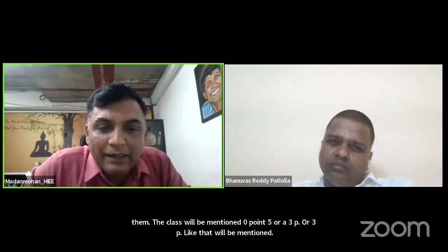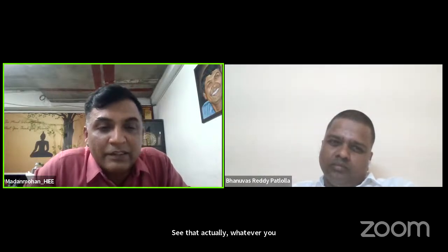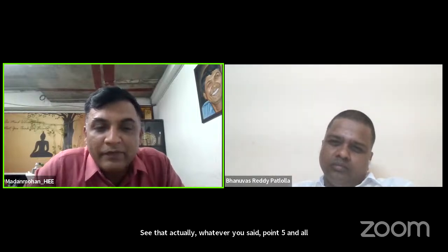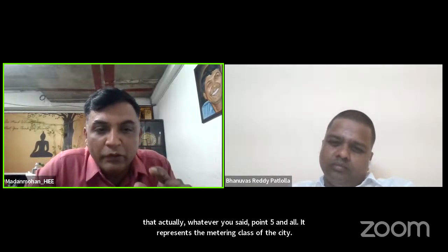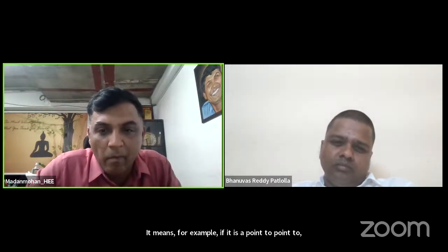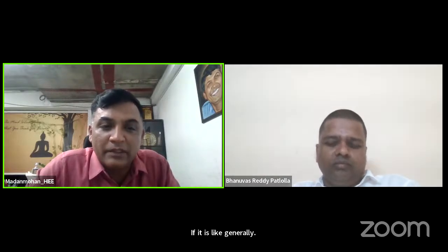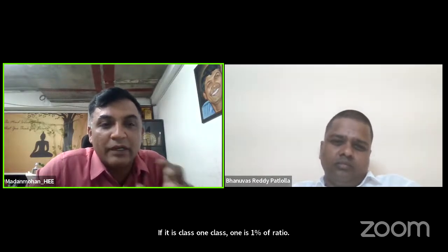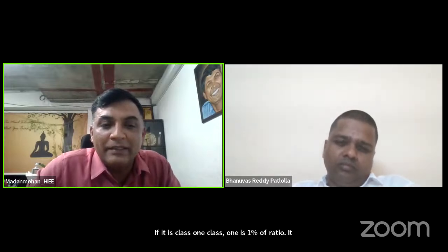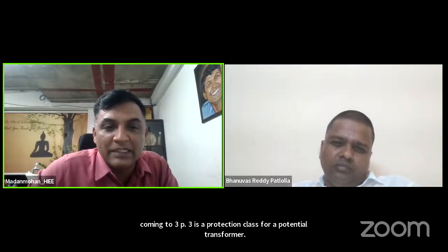Whatever you said, 0.2, 0.5 and so on, represents the metering class of the CT. For example, 0.2 represents the ratio error of the CT, 0.2% ratio error. Generally, class 1 is 1% ratio error. It represents the ratio error of the CT. Coming to 3P, it is a protection class for a potential transformer. 3 is 3% voltage error, and P stands for protection.